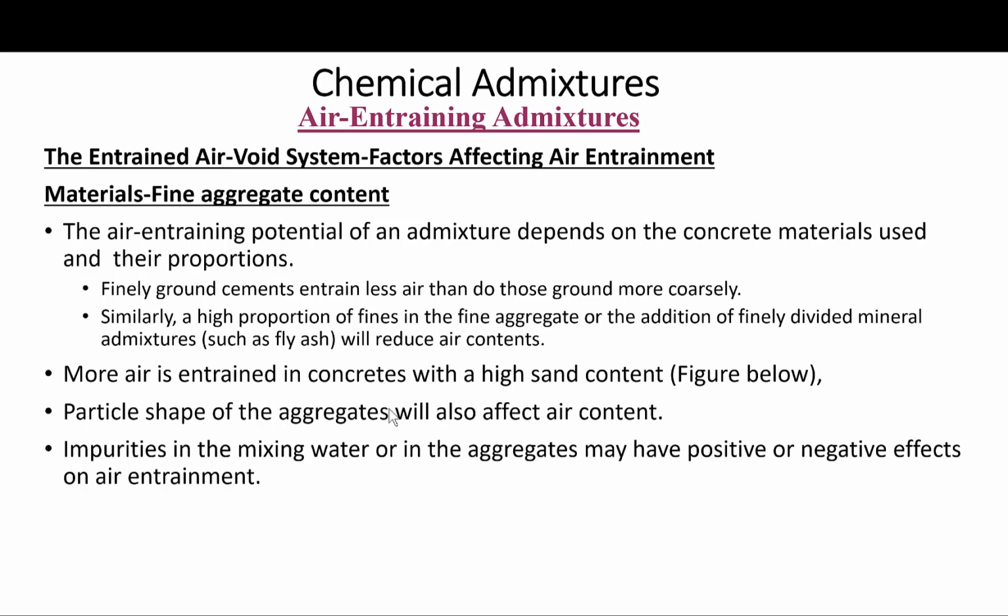So as far as the materials effect goes, what I just mentioned should be looked at: cement content, cement fineness, water cement ratio, the fine aggregate content of the total aggregate, the fineness of the fine aggregate, the use of mineral admixtures such as fly ash, which affects both generally because of its fineness and because of the carbon content, and also the use of other admixtures.